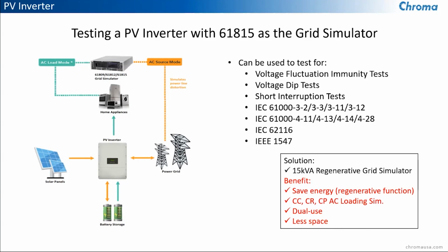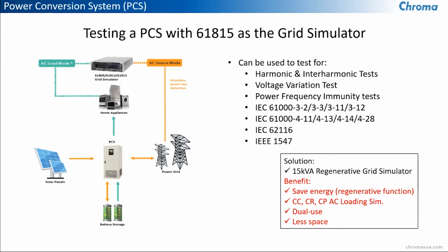And finally, we will be going over the PCS system. A PCS is a collection of electrical equipment that converts DC from a solar system to AC. It has monitoring devices and isolation switches that can isolate the solar energy facility from the bulk electricity grid during off-normal conditions that could jeopardize or damage either the facility or the grid.